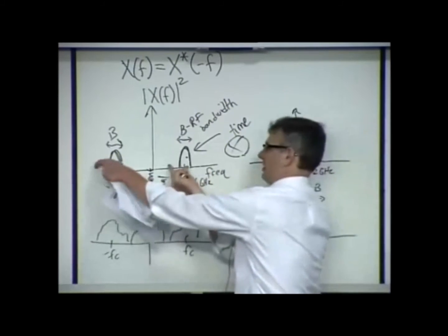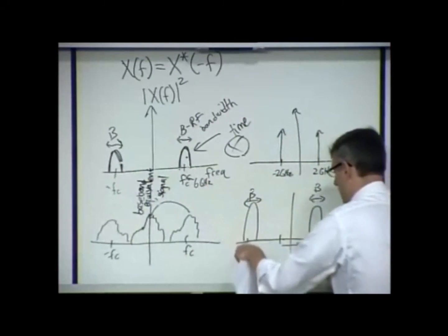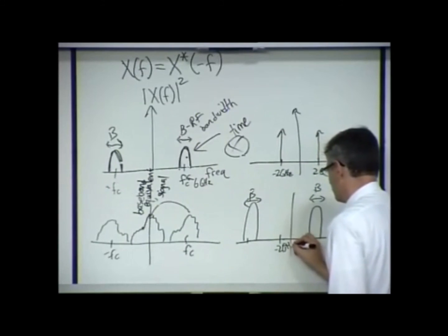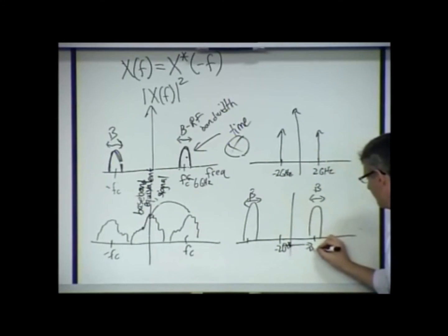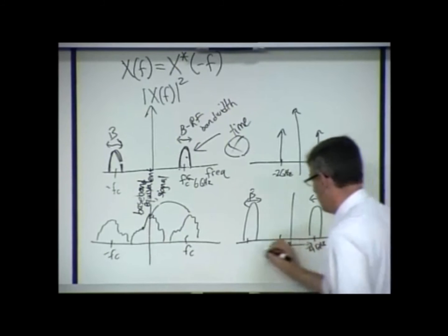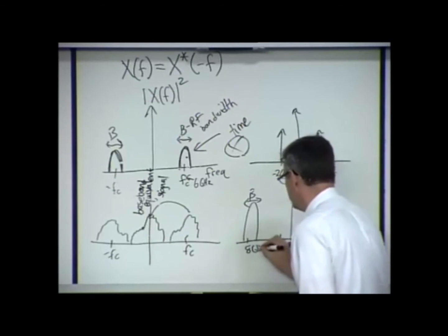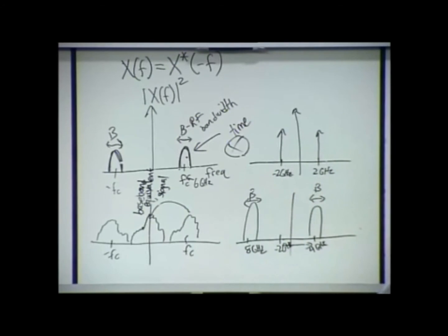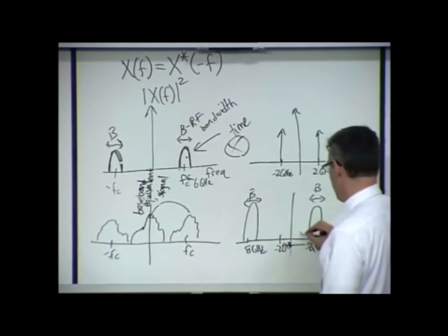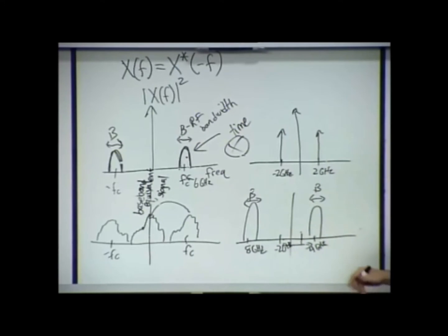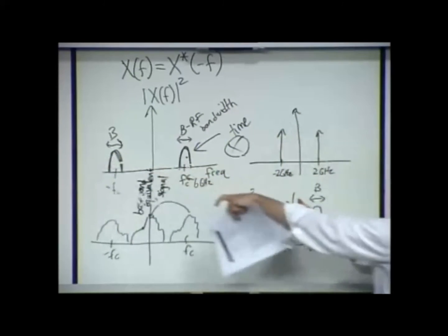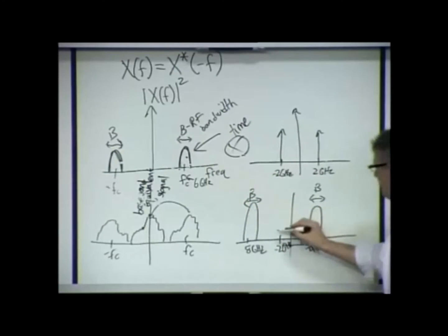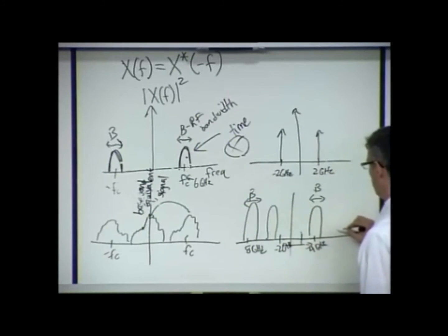So that's the first copy that I plop down at negative 2 gigahertz. That puts this peak at 4 gigahertz and this one at 8 gigahertz. And again, I have positive 2 gigahertz. I'm going to have to plop a copy of this signal down right there. That'll put a lobe there.